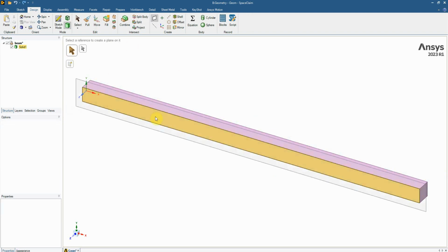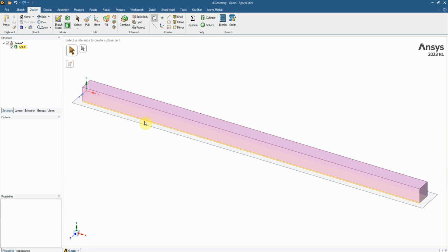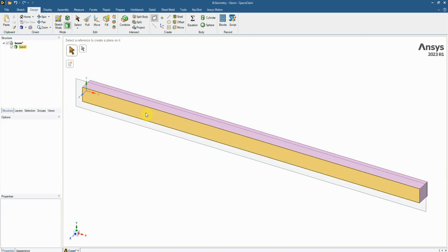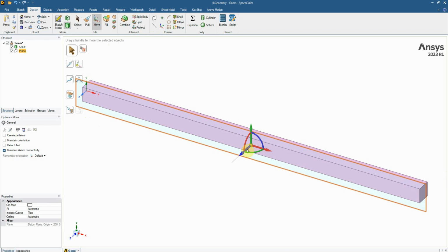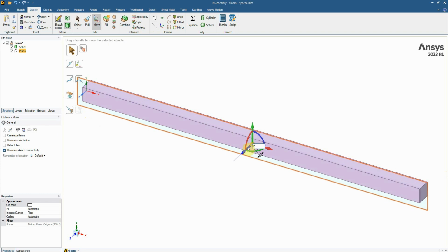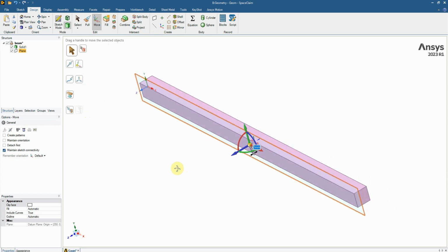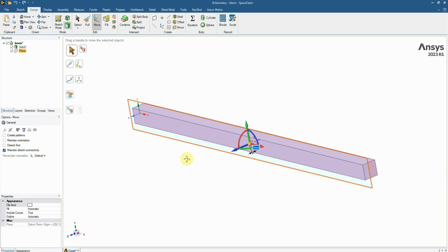We must select this Z face here to create the plane. Reason being is because every extrude we do for the shell fill will be in the Z axis. So select this, we create that plane. We want to now move this plane in the Z direction 2 millimeters. So you can see that there, it's in 2 millimeters.